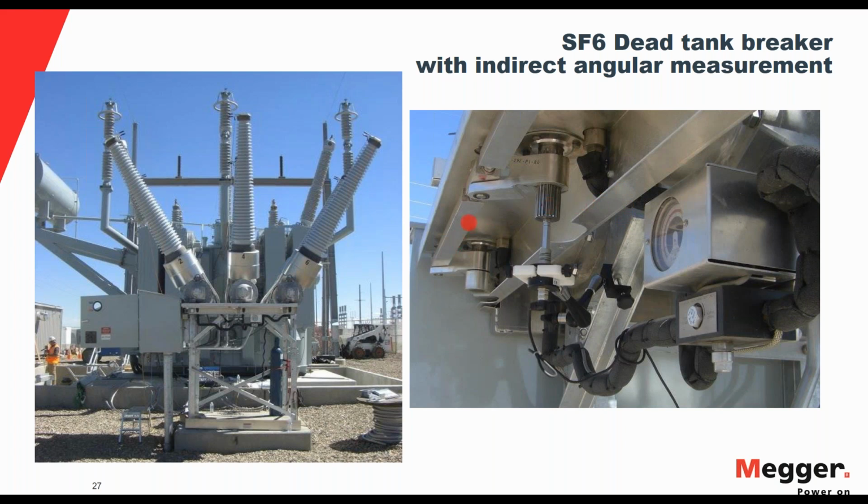So this arm rotates and helps open or close the breaker. This is a helping arm to it. So we connect it to the gear controlling this arm in an angular motion. So we are capturing the angle from the start to the end of the rotation using this transducer.